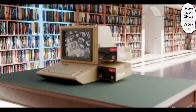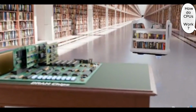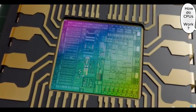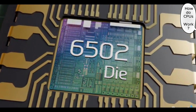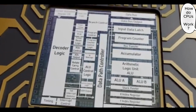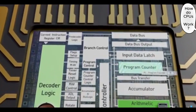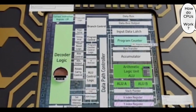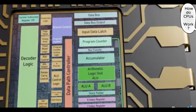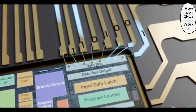Specifically, the floppy drives are the bookshelves, and then when we open up this computer, we see the DRAM chips, which are the cart. And then, going inside the 6502 processor, we find an integrated circuit or die which has the corresponding sections that we'll organize into an internal architectural diagram. In this diagram, you can see the instruction decoder, ALU, the program counter, current instruction register, the other registers, and a few other sections. Specifically, here's where the program counter is used to fetch an instruction, and here's where the instructions and data from the DRAM chips are bussed in and out.